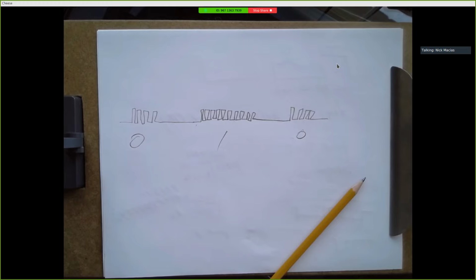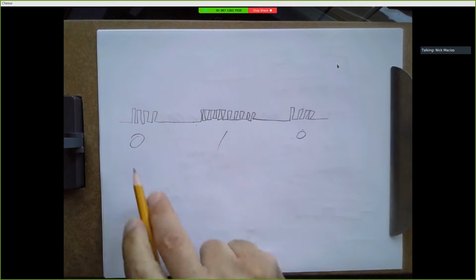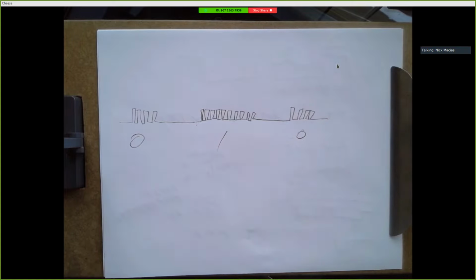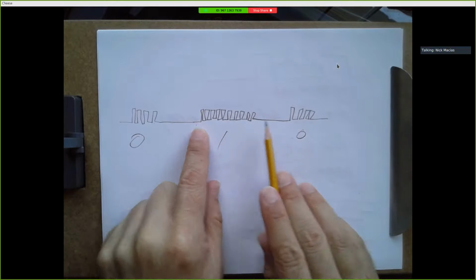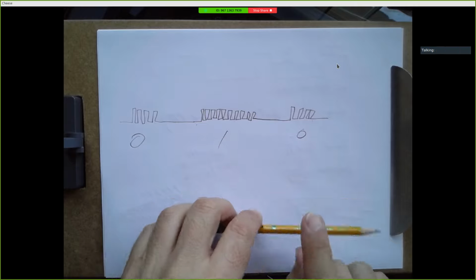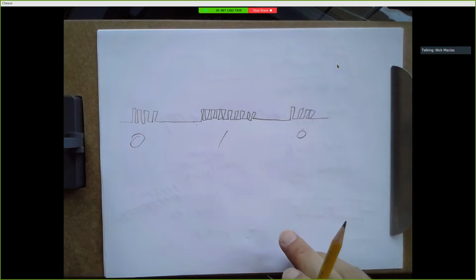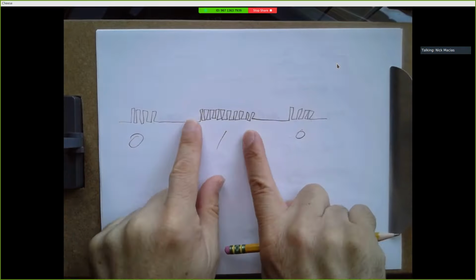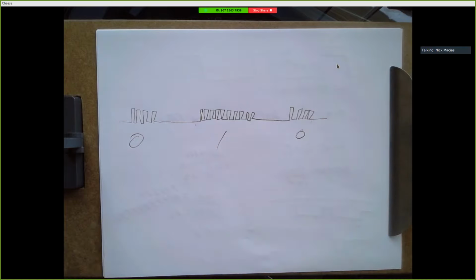8 bits that need to get transmitted to the TV's receiver, and it does that by generating a signal, typically 40 kilohertz, and it generates a short burst or a long burst to code up 1s and 0s. Now if you want to do that from a microprocessor, there's sometimes hardware support inside a chip that will let you specify this behavior, but you can do this by hand.